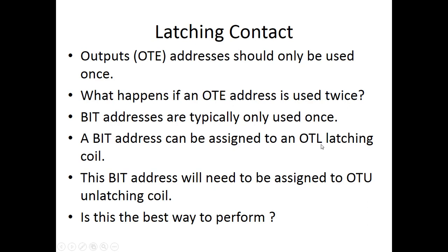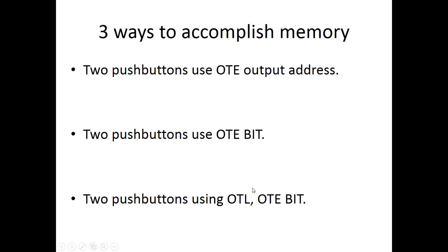But what these OTL and OTU do is simulate the latching relay that we learned about in 131. The OTE is just the output energize. These also go on to the coils in a program, but it's latch and unlatch. It says what's the best way to perform.